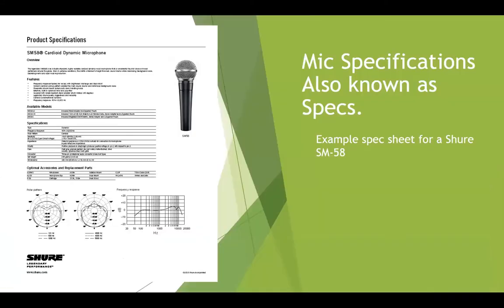The next thing is, and I'm going to see if I can, oh, there we go. Zoom in on this. So here's your polar pattern. Remember, it said cardioid in the text, right up here, but here's where you can actually see that cardioid shape, just to confirm it. You can also see the dotted lines for the different frequency response. You'll notice at 125 hertz, the solid line at the back, it's almost omnidirectional, right? But at very, very low frequencies. Anything above 500, which is getting into the range of most audio, is immediately cardioid, from that point forward.